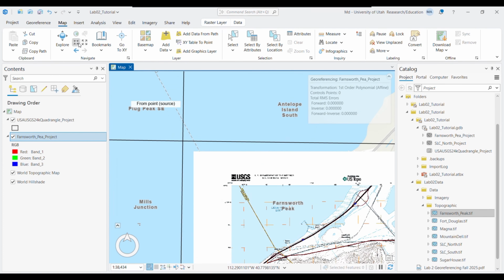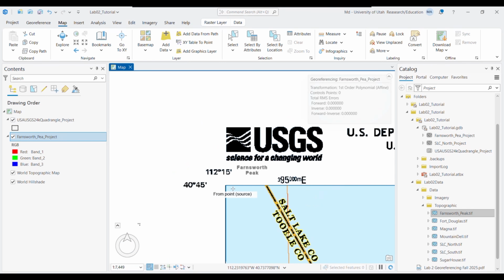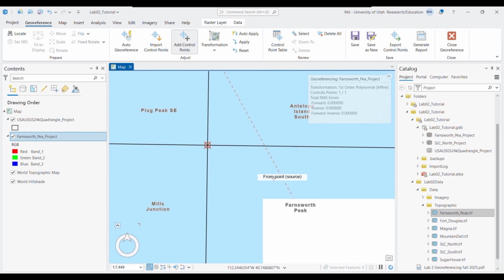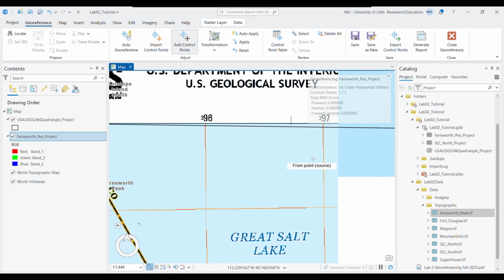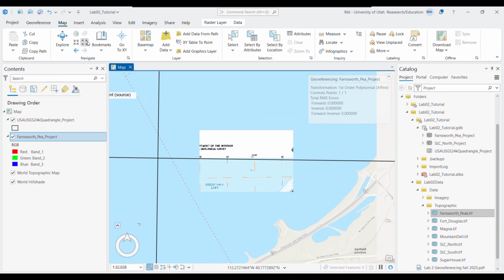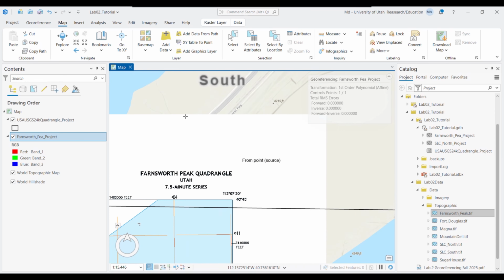I will just georeference it in the same way, and these are quite easier to georeference because we have the intersecting grid lines very visible in these images, but you will face some problems digitizing some images which do not have these grid lines.